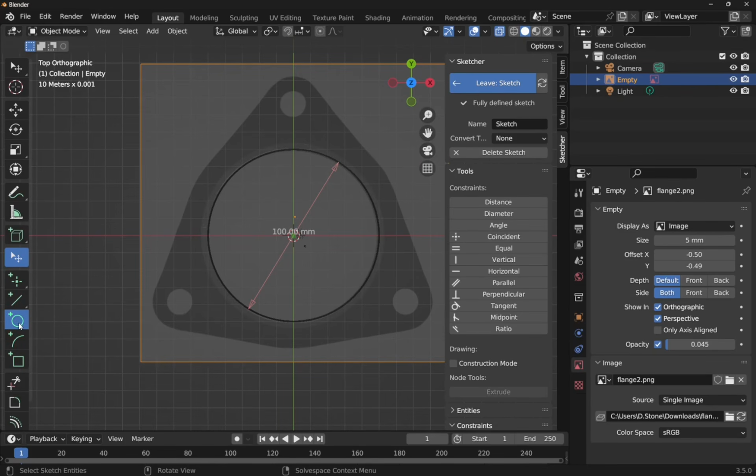So first of all, let's get some circles in here. Let's click on Add Circle, and we'll create a circle that's in here like so. So one circle. Now we need to place some distance away from this point and this point in here. If I come in here, you see I've selected all sorts of things, so I can't shift select them. If I roll over this 100 millimeters and it highlights, click it and pull it right out the way. So we've got nothing in here.